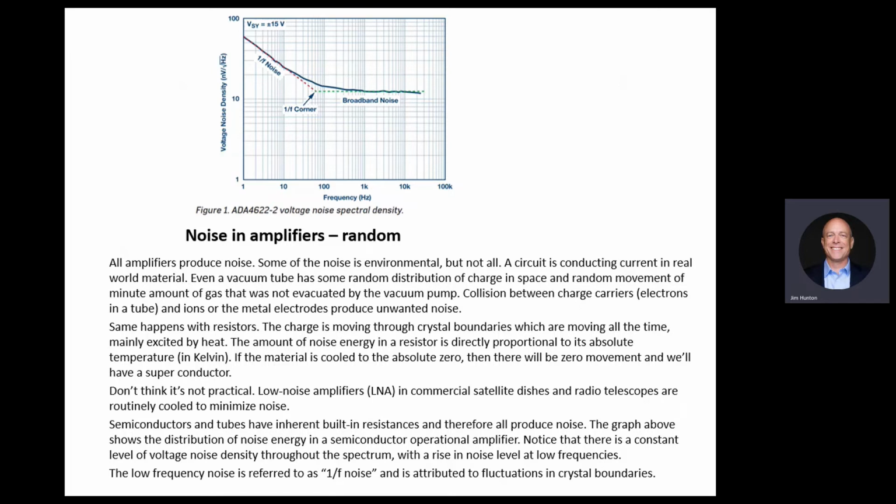You have noise generated, but you cut it down with the curve. But still, you have to look at the device and see how much noise inherently the device has and how much low frequency noise it has. Because remember, the low frequency RIAA, we amplify the most. Even though it's a very small range of the audio, we have a lot of amplification for it. So you really want to cut it down.